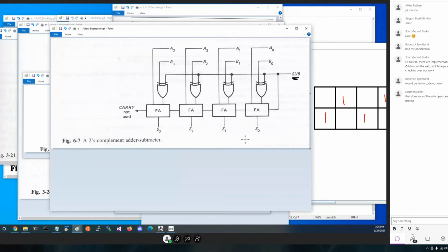Subtract serves 2 purposes. It operates as a controlled inverter signal, the thing that says do your inversion now, and it also acts as input to the first stage on the right's carry, so we can add an extra 1 to those inverted bits when we're doing a subtraction. And adding a positive number with a negative number, where we've inverted a positive number, we're going to be able to make it happen.